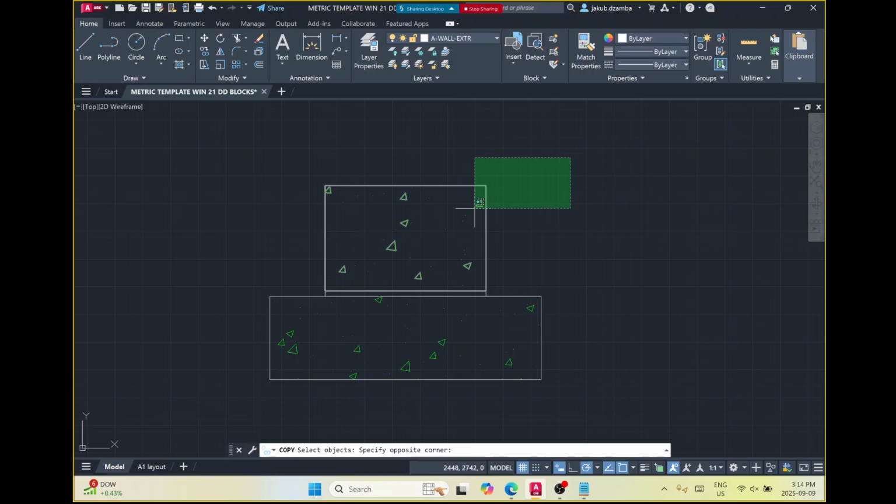There's two different selection methods. If I'm going from left to right, you have to encompass the whole object for it to become selected. If I'm going from right to left, then any object I touch, even a little bit, becomes selected. It doesn't matter which one you want to do. It's just two different strategies for how you select stuff. Sometimes you're going to be working in a big mess of objects and you want to be really precise, so you use one method versus the other.